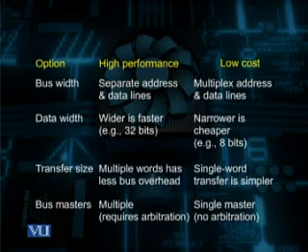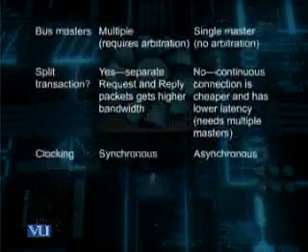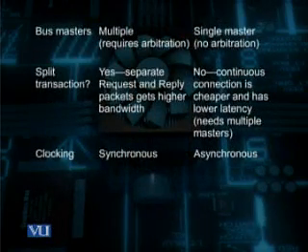The other parameters which are also important for the bus design are referred to as the split transition and bus masters. Based on the bus masters, multiple masters are used in high performance computing, and single master that involves no arbitration is used for low cost systems.